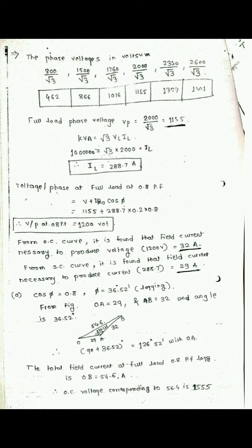So for that 54.6, connect this value to the open circuit characteristics curve, and it gives the corresponding open circuit voltage for 54.6, which is 1555.